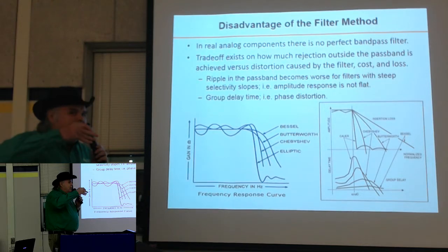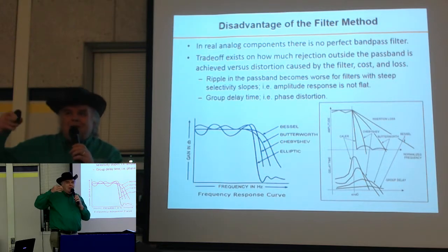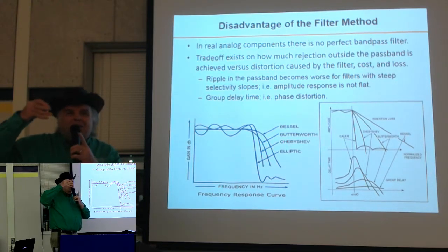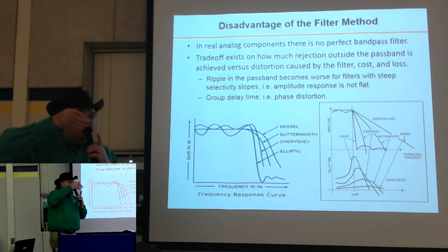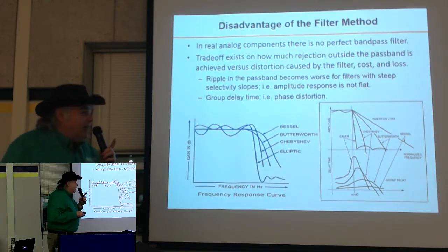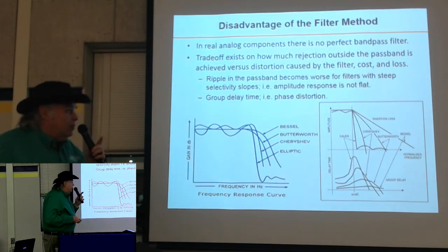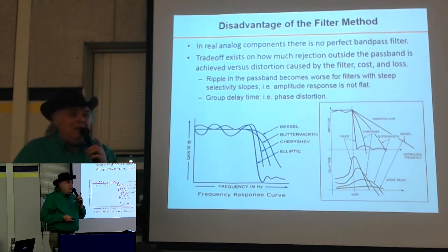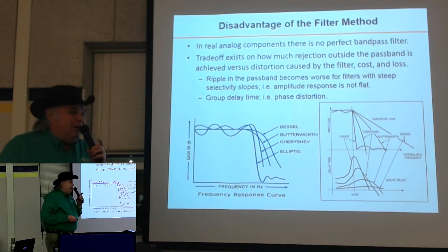Particularly if you're running wideband digital, that becomes a problem, because all of a sudden this symbol and that symbol at different frequencies are not getting through the filter at the same time. And it can actually smear the symbols that you're trying to get digitally, and cause a lot of errors in your data transmission, and it's all caused by this group delay issue in your filter. It's also rough on your ears if you're listening to sideband and you have a lot of phase distortion as well. It's not real apparent at first, but it wears on your ears.